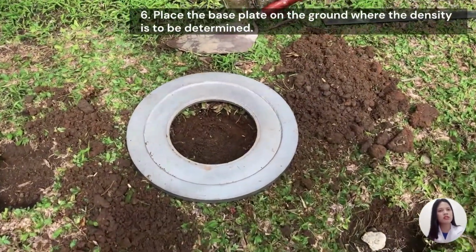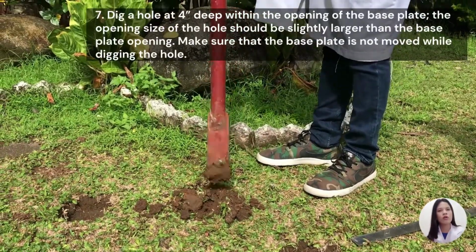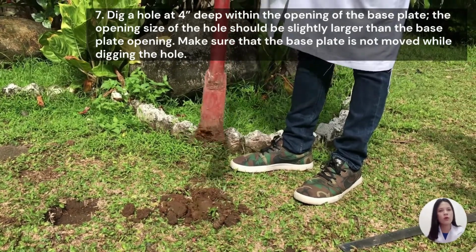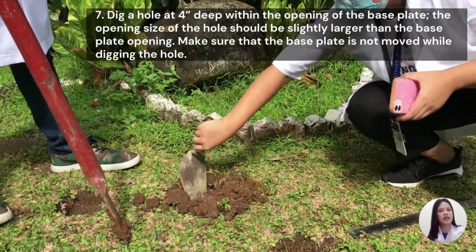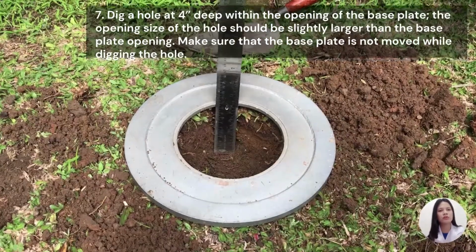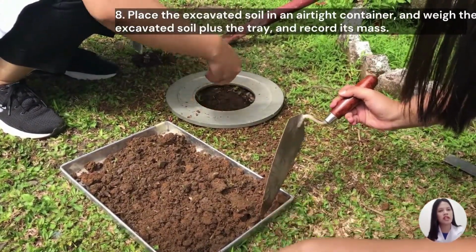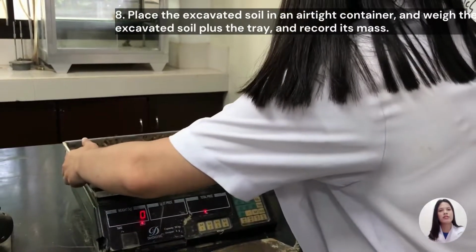Place the base plate on the ground where the density is to be determined. Dig a hole 4 inches deep within the opening of the base plate. The opening size of the hole should be slightly larger than the base plate opening. Make sure that the base plate is not moved while digging the hole. Place the excavated soil in an airtight container and weigh the excavated soil plus the tray and record its mass.